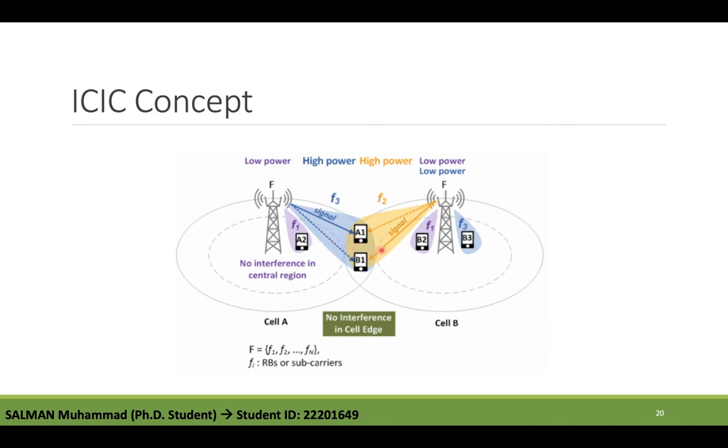Base stations that support this feature can generate interference information for each frequency resource block and exchange this information with the neighboring base station through X2 messages. From these messages, the neighboring base stations can learn the interference status of the neighbors and allocate the radio resources, for example, frequency, transmit power, etc., to their UEs in a way that would avoid the inter-cell interference.